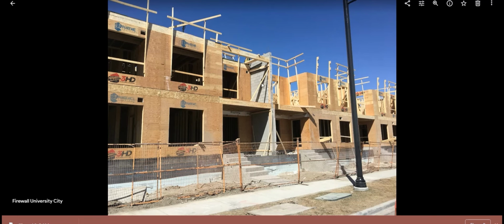And so the primary purpose of why, for example, this building would have this firewall here is because likely if this wall wasn't here, this building couldn't have been made of combustible construction. So if that wall was not put there, very likely this building would have had to have been of non-combustible construction, so steel construction or concrete construction. And they wanted to build out of wood. So by putting this wall in there, that enabled them to build this building out of wood.